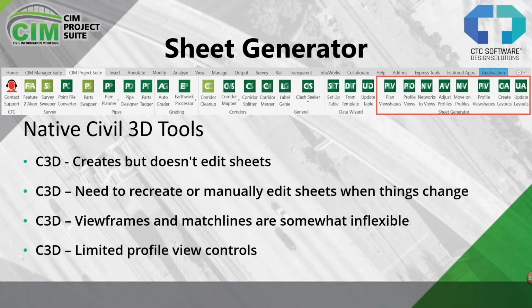So Sheet Generator, what does it do? It's been created because Civil 3D creates but doesn't edit sheets. In Civil 3D, you need to recreate or manually edit sheets when things change. And view frames and match lines are somewhat inflexible, and they have limited profile view controls.